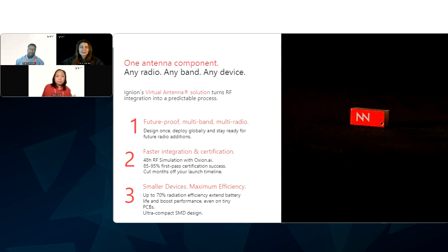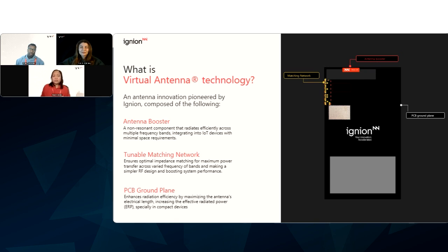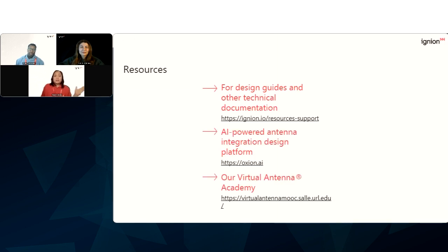Now, why is it called virtual? It's simply because the antenna booster is non-resonant. The final resonance is shaped virtually through the PCB layout and matching network, so it turns the entire ground plane into the radiating element.